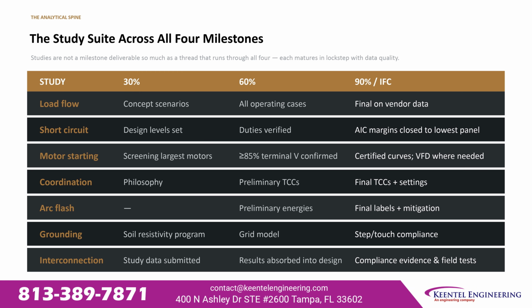Power system studies are not a milestone deliverable. They run through all four, maturing in lockstep with data quality. Load flow covers concept scenarios at 30%, all operating cases at 60%, and closes on vendor data at IFC. Short circuit sets design levels at 30%, verifies equipment duties at 60%, and closes available interrupting current margins at IFC.